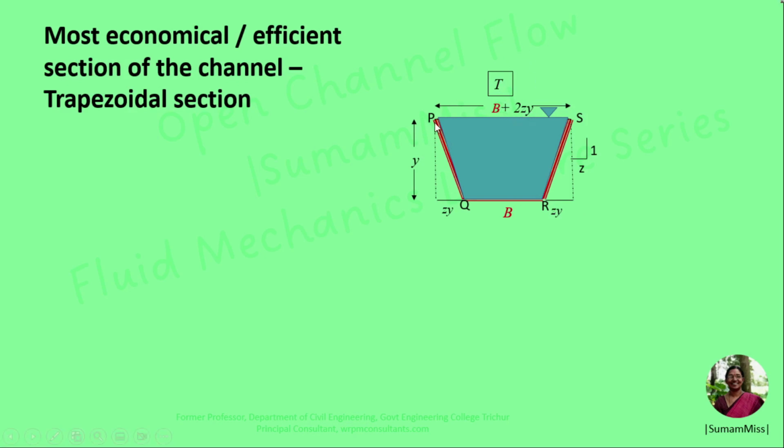Similarly, the length of the sloping side PQ: PQ square equals y square plus zy square, or PQ equals y into root of 1 plus z square. So the area of this trapezoidal channel section equals B plus zy into y, and the wetted perimeter P equals B plus PQ plus RS, that means B plus 2y into root of 1 plus z square.